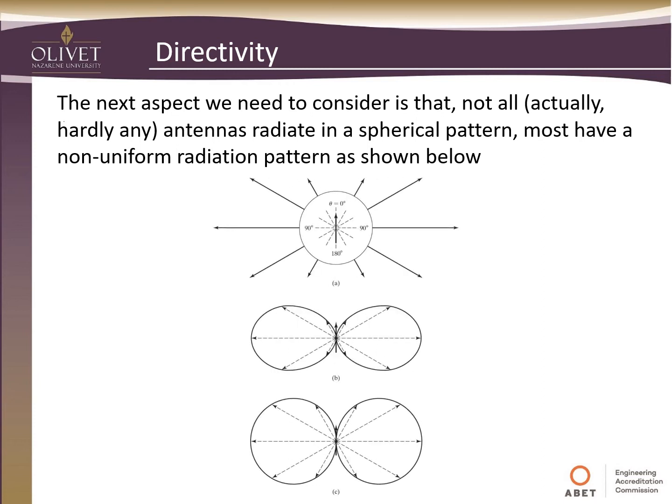And as an example, here's our Hertzian dipole. So if you were to take a meter out here and measure the field, I believe this is the field pattern and this is the radiated power pattern. You measure out here, you're going to measure basically nothing until you swing around here with your meter, and then you'll start to measure here a little bit of field, and then it gets more intense, and then it drops off again as we move around. So it's not in a perfect circle. These vector lines kind of give you a magnitude representation of the field intensity moving around there.